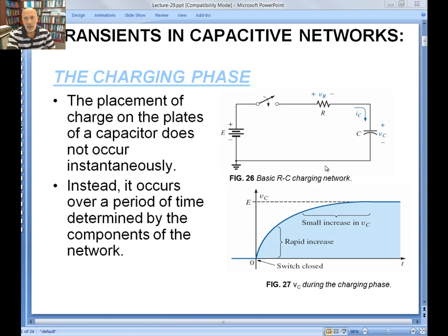But once we put in another storage element, such as an inductor that we're going to discuss in the next chapter, the system becomes second order. A second order system could oscillate up and down and not settle down. But all first order systems, fortunately, behave exponentially, just like you have it in here. This is called a transient response. Everything that is a function of time will have a transient response and then will reach a steady state response. For the capacitive circuit, the transient response is an exponential function. As I said earlier, all first order systems behave exponentially.